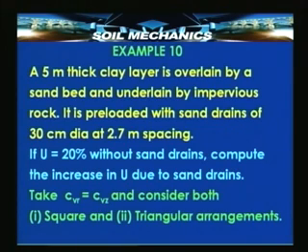For convenience, let us take Cv for vertical direction as well as radial direction as equal, and as far as the sand drains are concerned, which are of 30 centimeters diameter and at a spacing of 2.7 meters, let us consider both possible arrangements, that is the square and the triangular arrangements, and then find out if U is 20%, what is the corresponding U with radial consolidation, and therefore how much improvement is taking place in U.